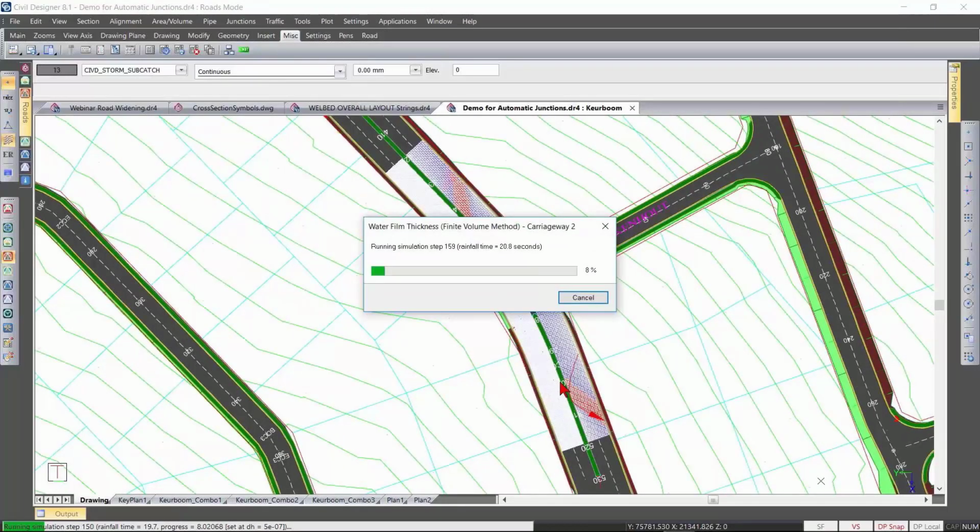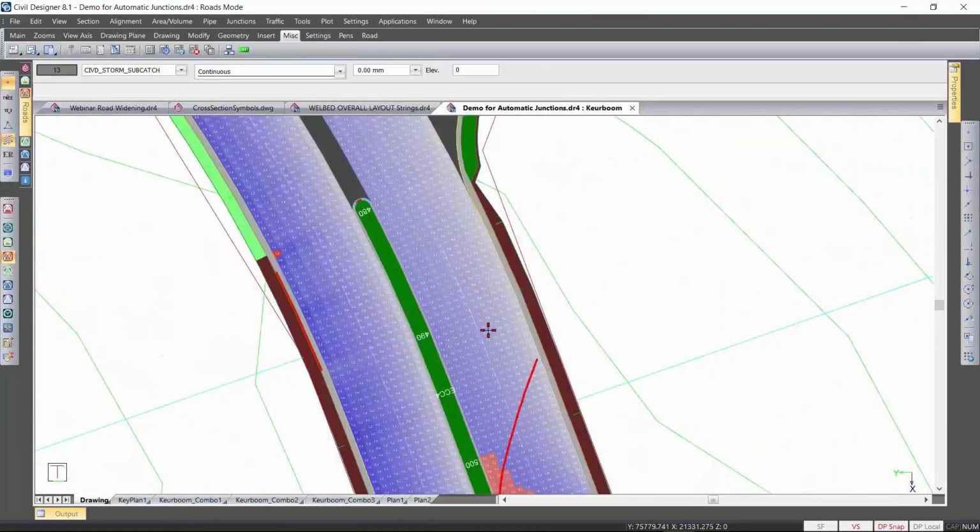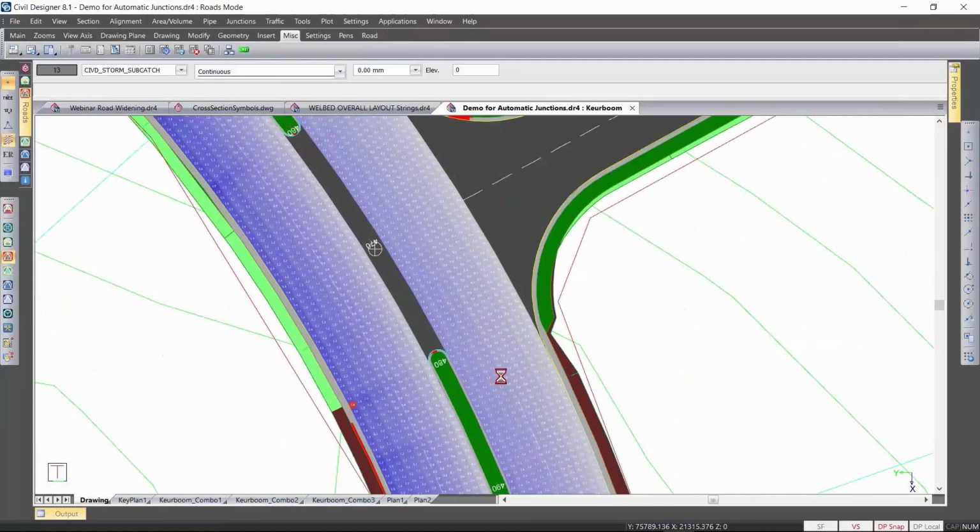areas. The optimum chainage range for a realistic analysis is between 200 and 400 meters. It depends on your road properties, your road widths and crossfalls, and then a maximum of about 1,000 meters is generally recommended. Okay, so it's run both sides, and you can see, if I zoom in a bit, the shading it's done.